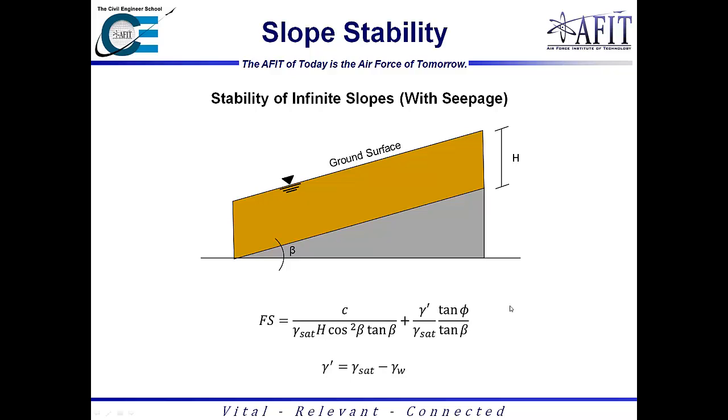So then we can also get into seepage, where we'll actually have to change our unit weight. Instead of using just the regular unit weight of the material, we'll have to use the saturated unit weight or the effective unit weight, just depending on which portion we're actually dealing with. As a reminder, the effective unit weight is equal to the saturated unit weight minus the unit weight of water.